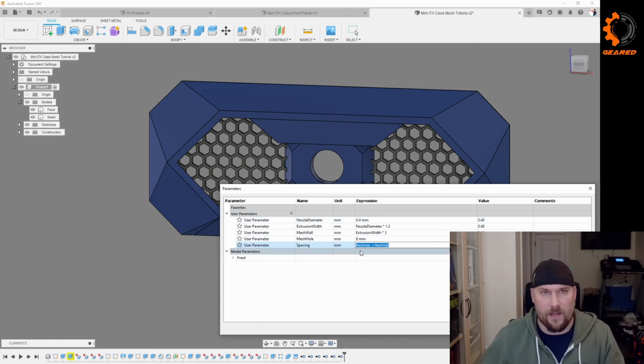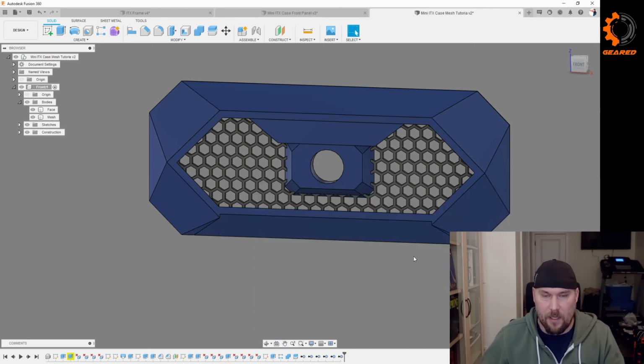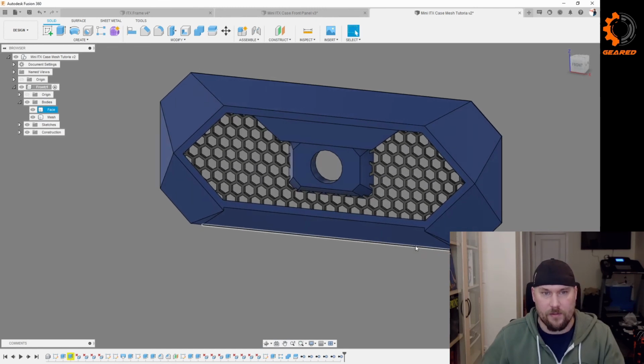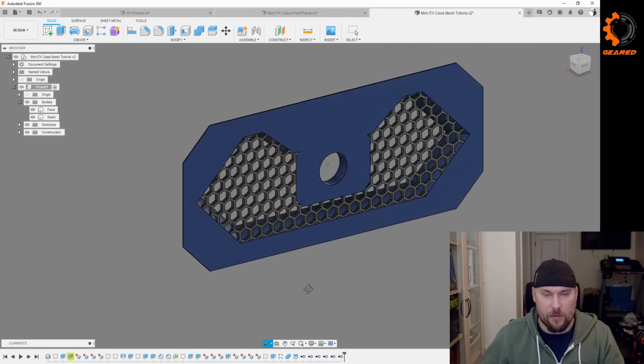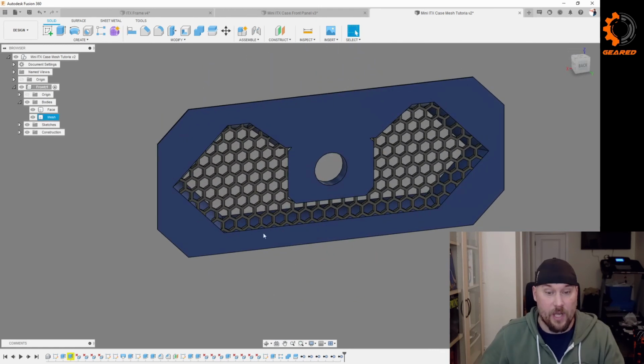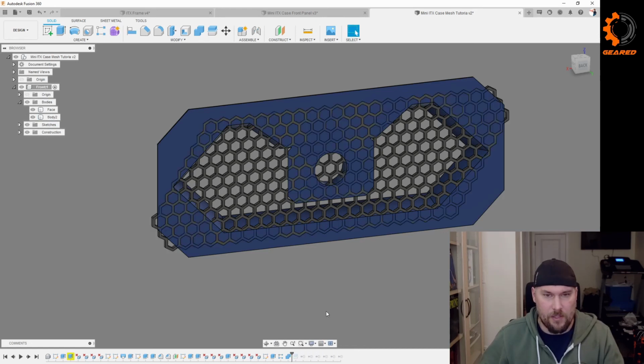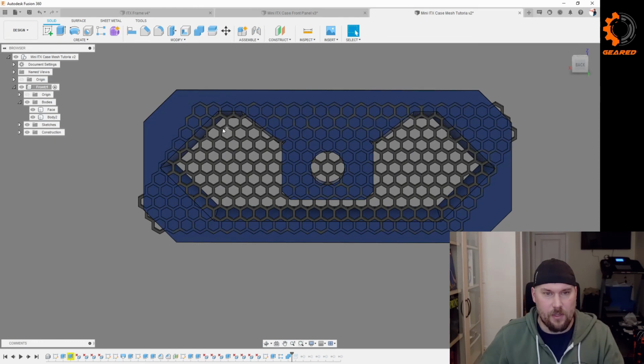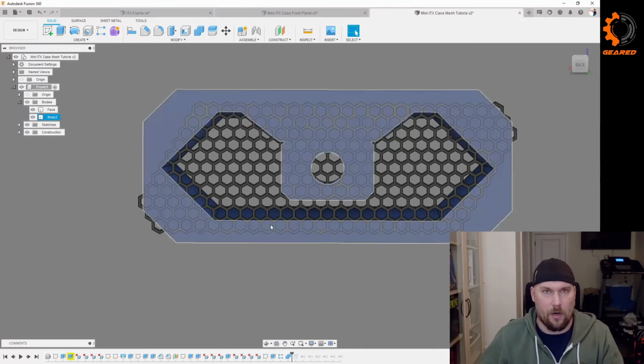They are fantastic for being able to keep your design parametric, but sometimes they don't quite work out the way you want them to. But the good thing was we could see down here at the bottom where the errors were happening, and most of those errors were happening because we were trying to change the space on something that we had cut up. So in most cases, what we could do is roll back our timeline to here, make our changes to the parameters we want to get this dialed in, and then we probably would have to just redo our split body.